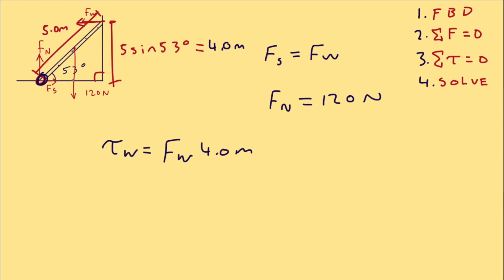And you might be asking, why is the lever arm not 5 meters? Because the pivot's here, isn't it? Not here. Here's the thing. This force is not perpendicular. It's at an angle, see? By definition, the lever arm is the perpendicular line from the pivot to the line of action, the distance there. And that's this wall. So 4 meters.